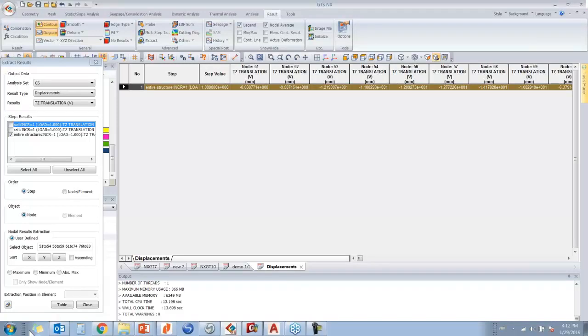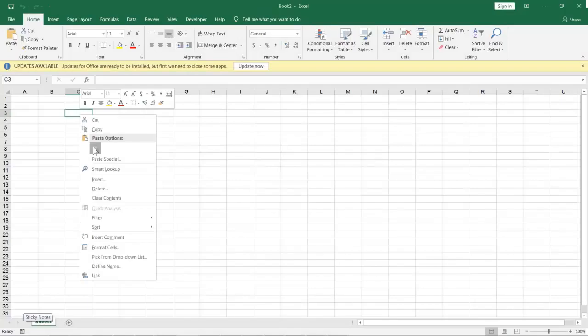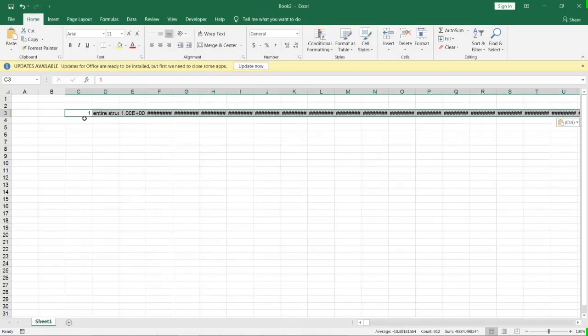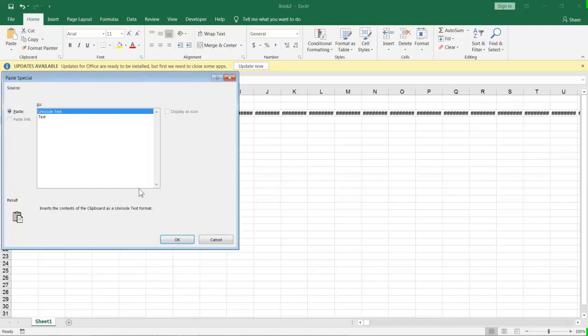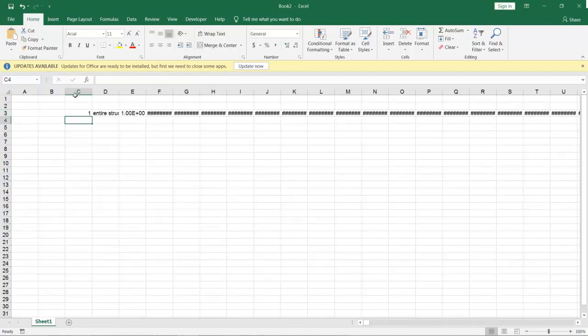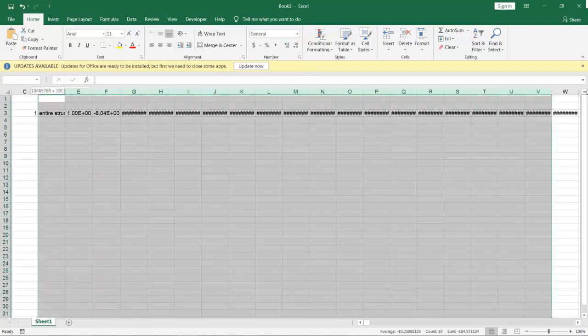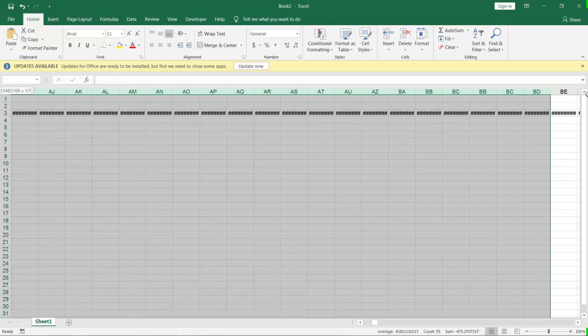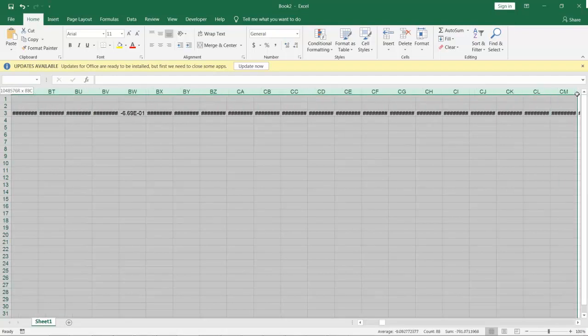And with the help of these, we can go ahead and even use the paste special option, and then we can just modify this information. Okay, so basically we can get the displacement values from Midas GTS NX and then use it to find the modulus of subgrade reaction, which will be then further utilized to apply the point spring supports in Midas Gen program.